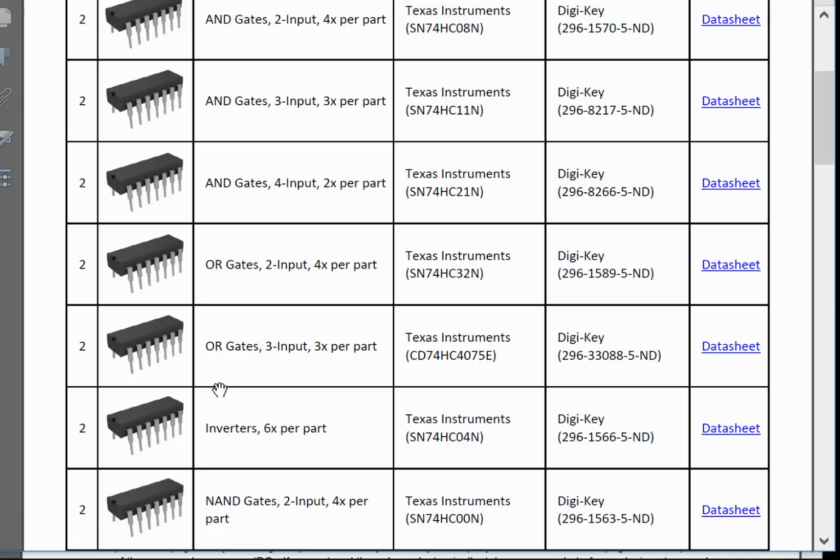Then you're going to go to the minterm portion, and remember you've got 4 3-input AND gates that represent each AND term, where each AND term is one of your minterms. Well, now you need a 3-input AND gate. So do you have that in your parts? Yeah, you do have it. Look at right here. The HC11 has 3-input AND gates. Now there's only 3 per part, but that's okay because there's 2 of them in your kit. So you're going to need 2 of these gates right here to implement the AND terms.